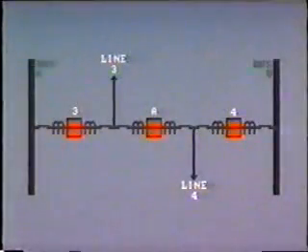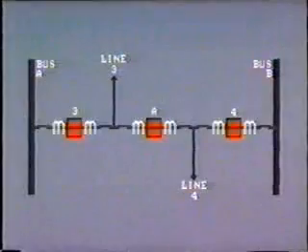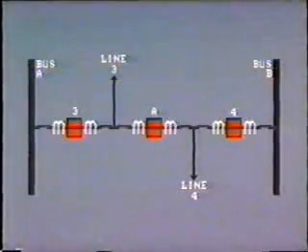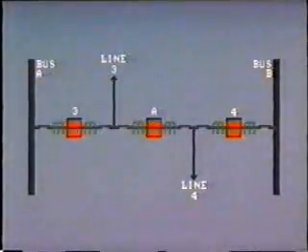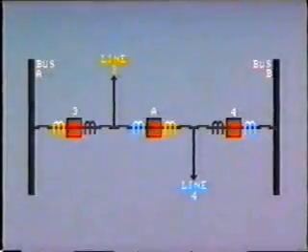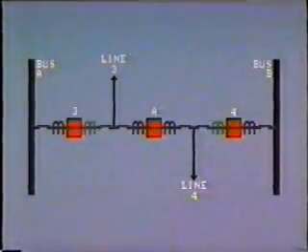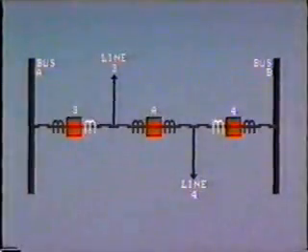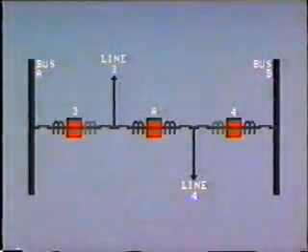in parallel. You will observe that CTs are installed on all breakers so that both differential and line protection can be provided. Line relays are served by the outboard CTs of the line breakers. Bus differential relays are served by the outboard CTs of the bus breakers.